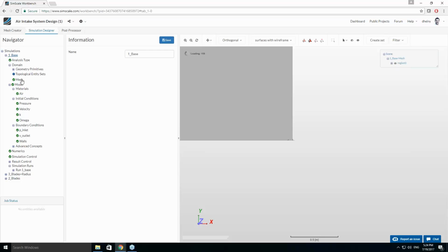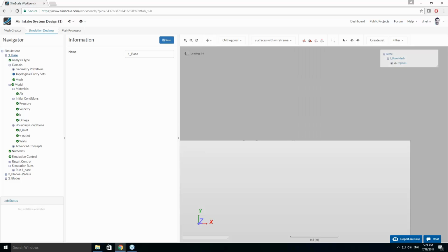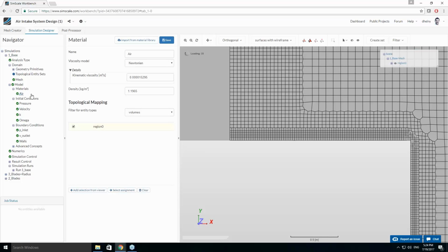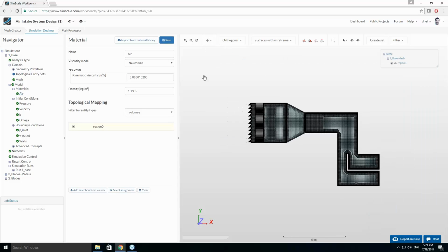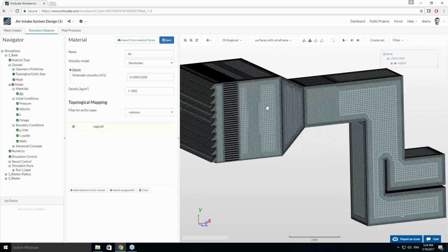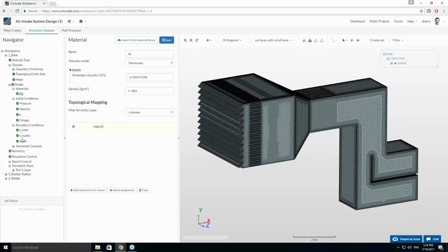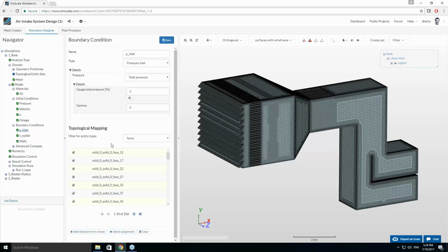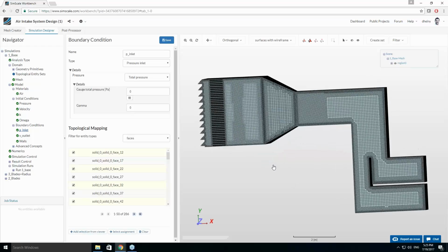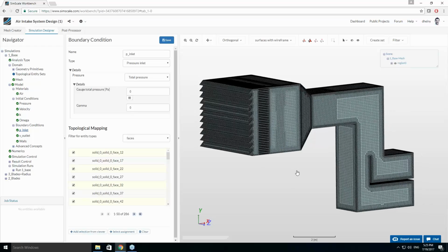And I want to walk you through once, so just the most important things. So first I specified a material, right? In that case it's air, so I specified air as a material, and then the rest, the initial conditions, I left them as is, and then basically I just set up 3 boundary conditions, which essentially means how does your system behave at the ends of the computational domain, so at the boundaries of what you want to simulate.